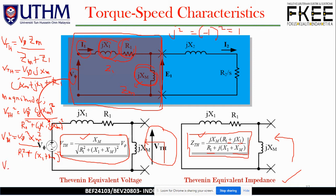To remove the squared, so we have VTH equal to, we try to square root everything over here. So now we have V phase XM over square root R1 squared plus (X1 plus XM) squared.